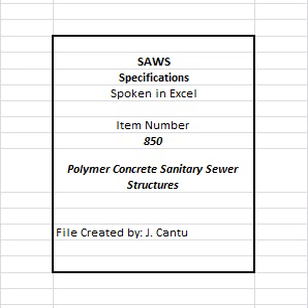8. Marking and identification. Each piece or component of the manholes and structures shall be marked in letters no less than 1 inch in height with the following information. Markings shall be legible and located in a place within the manhole or structure. Tag and slash or stamp shall be placed in a location that can clearly be seen within the manhole or structure. Manufacturer's name or trademark. Manufacturer's factory location. Manufacturer's serial number. Production date. Manhole length. ASTM designation. Installation assist marks, vertical lines 90 degrees apart at base of manhole.